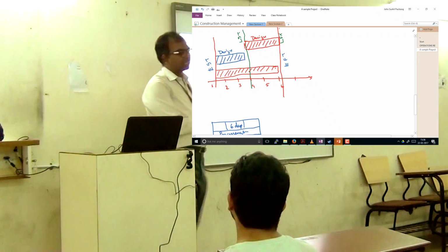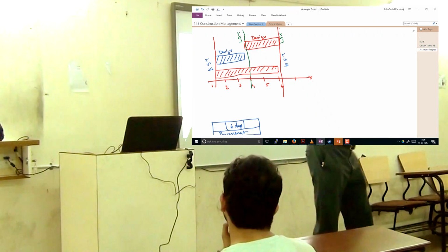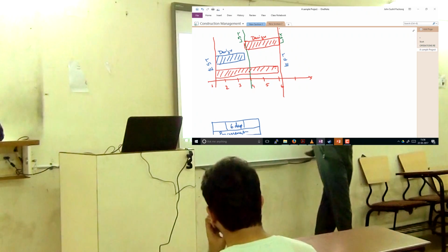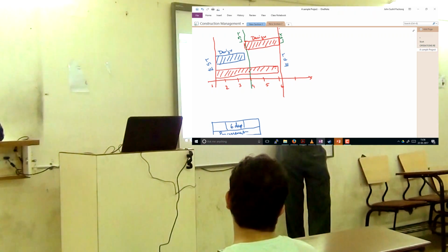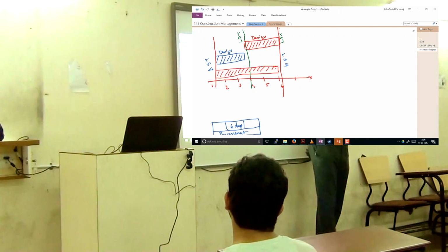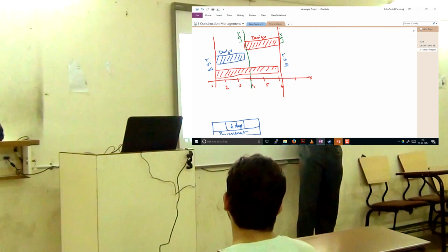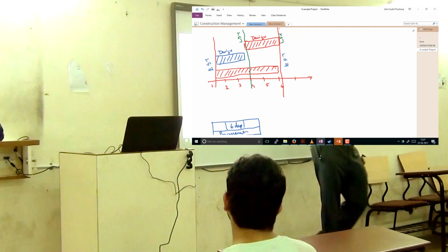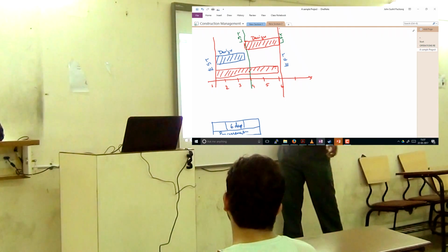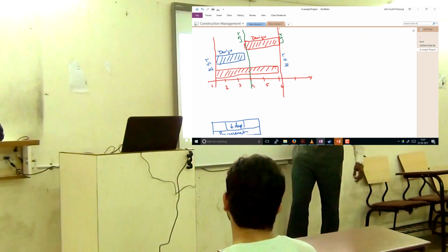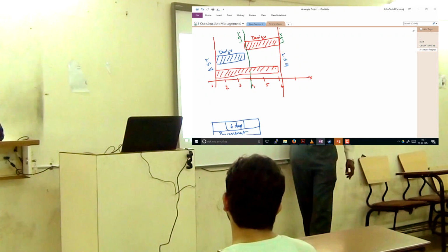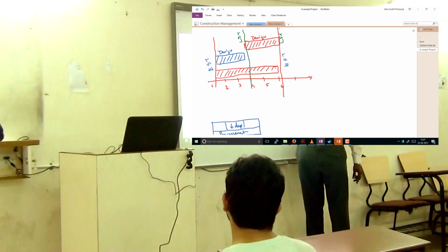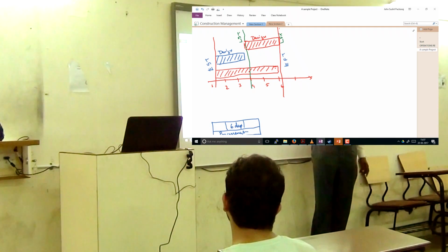Okay, so is this concept clear to you? I can start this activity at this point in time. That is the earliest I can start this activity, because the customer or the owner, your boss, is telling you to start the work on such and such day. For example, start it on 22nd of March. So you cannot start it on 21st of March. So this becomes the early start, and then if I add a duration, it will come to a point which is the early finish time. Now there's one observation which I'd like you to make. Whatever I do, this is not governing the finish time.